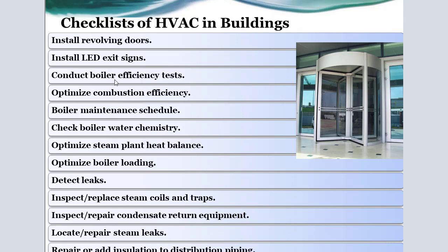Also conduct boiler efficiency tests, optimize combustion efficiency, schedule boiler maintenance, and check the water entering the boiler system in order to reduce corrosion inside the piping system.